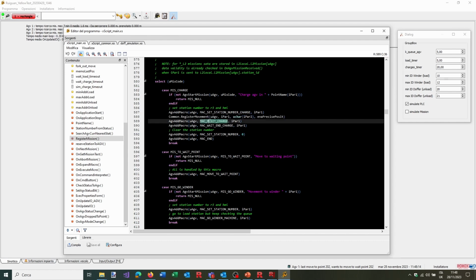Finally, there will be a macro to make a positioning to the charge point. In this positioning macro, we will, for example, enable the relay of the battery loading, and we will exchange some data with the PLC to ask the charger to start charging us. Then we will wait for the RP1, the Robox controller, to tell us that the battery has been fully charged.